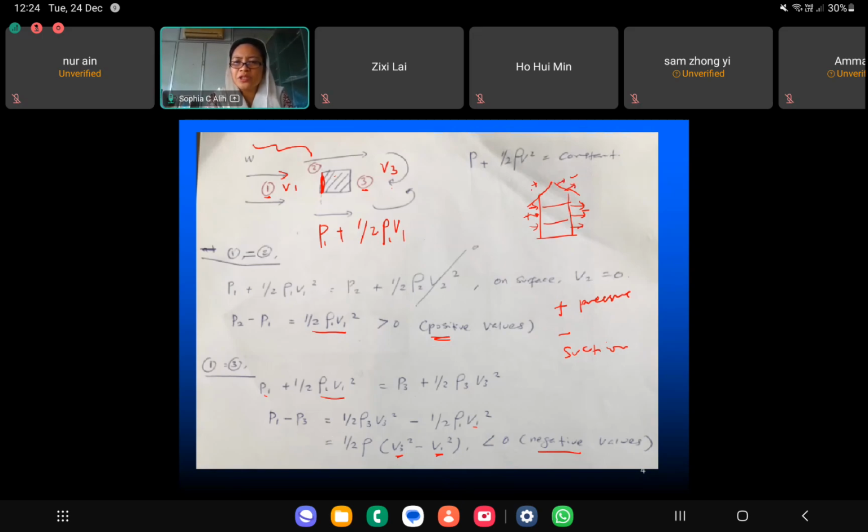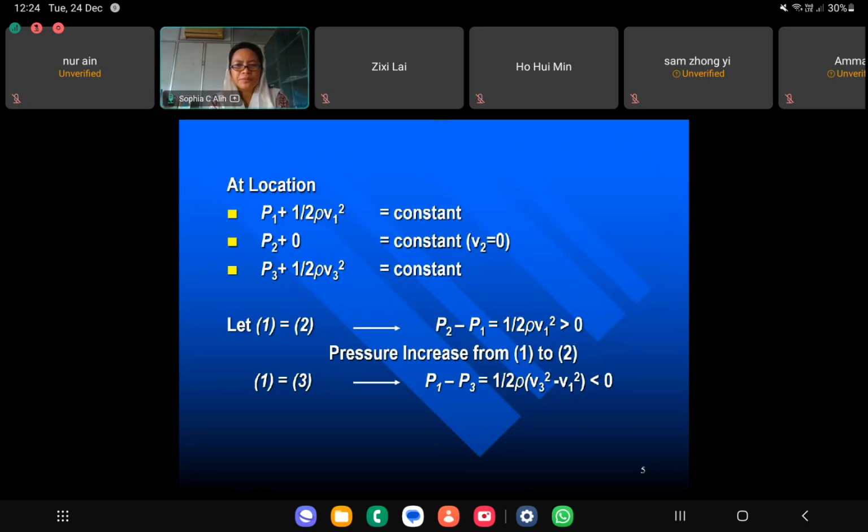And here also I have suction, and here I have pressure. Either you show the notation with plus or minus, or with arrows. An arrow pointing into the structure is pressure, and an arrow going out from the structure is suction. So there are two values when it comes to design, whether it's pressure or suction.